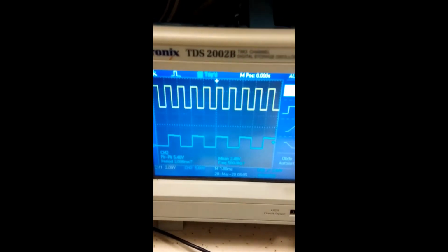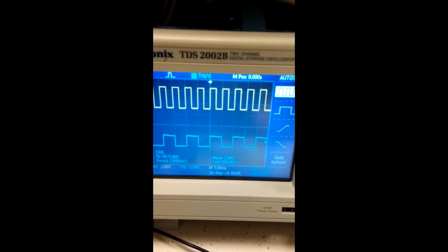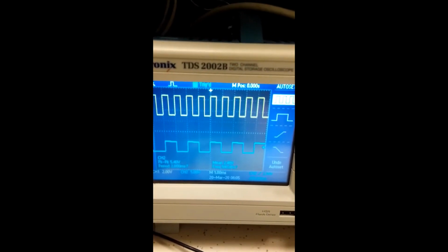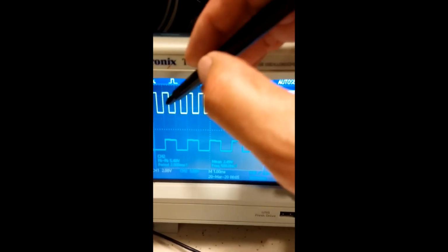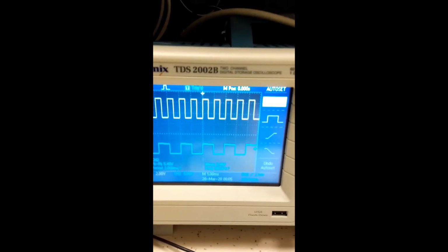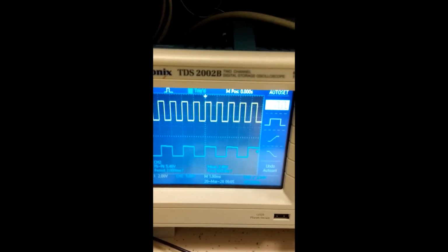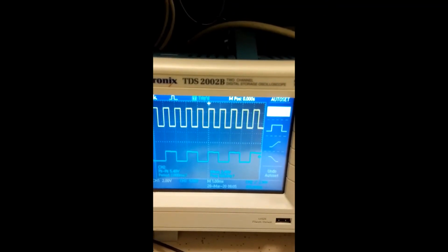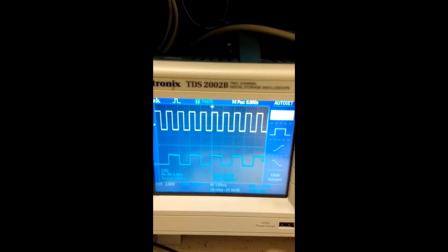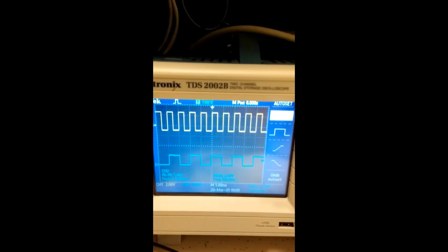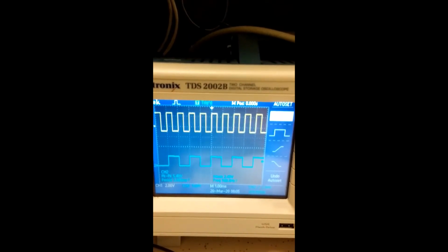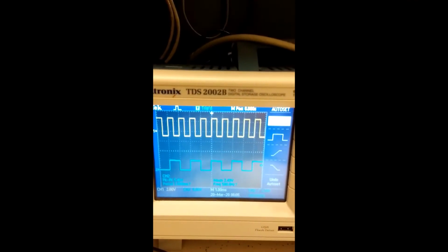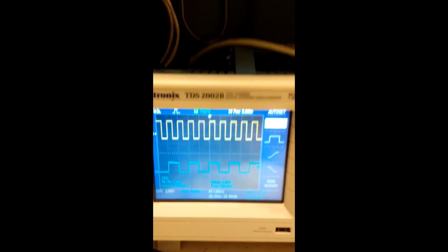So this is called the flip-flop. So the first pulse changes the output to high, and the next pulse changes the output to low. That is what it means. Okay, this is the result that you have. You can put in your report and then explain and describe what the circuit means by divide by 2. This is the meaning of the flip-flop as a divide by 2.